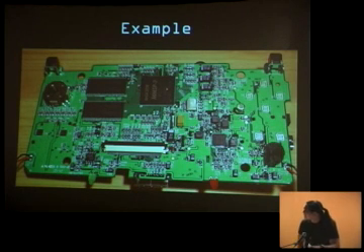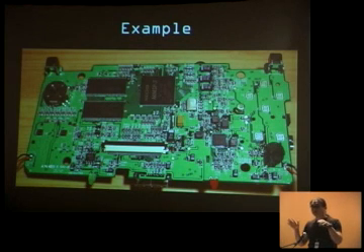JTAG is 5 pins, and usually they'll have a bunch of test points coming out, and it typically has a group of resistors hanging out the side, kind of like that. So there's 1, 2, 3, 4, 5. I wouldn't lay money on it, just looking at it quickly, but that's a good candidate because JTAG has 5 pins and usually has the terminator resistor that comes to the edge of the board. And so what you can do is when you turn it on, you can probe it during the power transit, you can see the clock happen and then it'll go quiet.